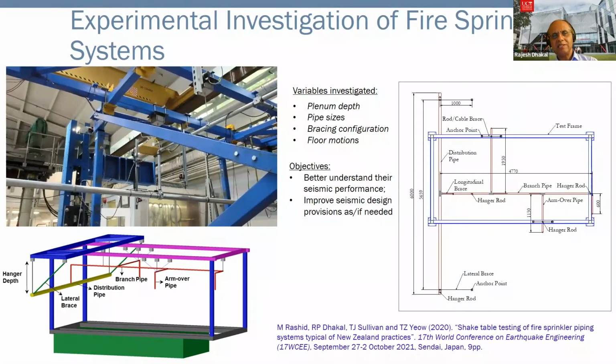We tested a large number of configurations of the sprinkler systems in terms of plenum depth, different pipe sizes, and different bracing configurations, and we tested them against different types of floor motions, like floor motions that have similar frequency characteristics to the piping system, meaning there is resonance, and there are non-resonant motions as well.